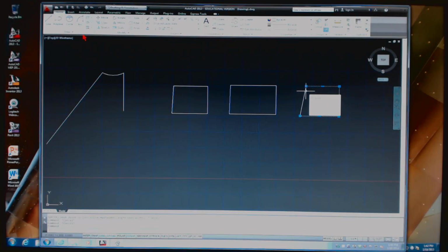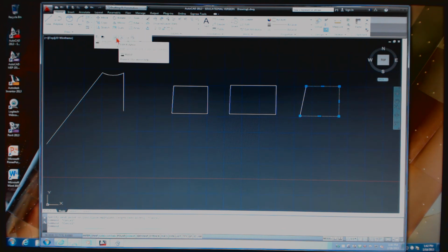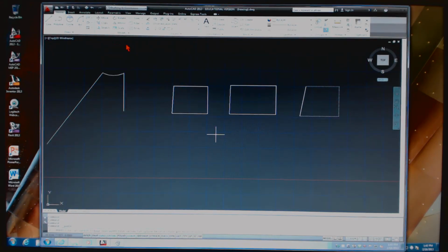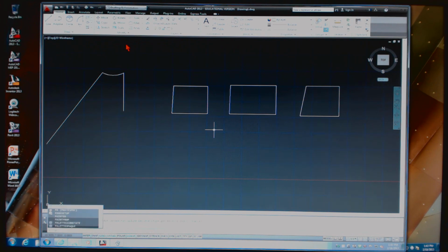And I'll show you. Is that 24? Is that 24 the edit? Yeah, 24 is going to be the edit. If you want to, click the icon, it's Home tab, Modify panel, click where it says Modify. And you can see right here, it's a pencil drawing a line, Edit Polyline, you click on it, or keyboard people, it's PE spacebar. Now, it says at the bottom, select your polyline. I'm going to select this as my polyline.